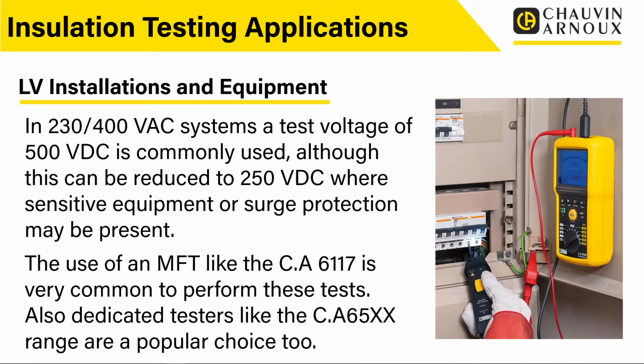So they are quite popular, particularly if you're doing specific types of maintenance work, where you're not doing full electrical installation certificates and full tests all the while, but you might be doing bits of fault finding where carrying out insulation resistance testing is useful. So you might be using a multifunction tester, you might be using a dedicated insulation continuity tester to carry out these tests, but this is a very common piece of equipment, and this is the sort of testing that an electrician would be doing day in, day out on this type of installation.